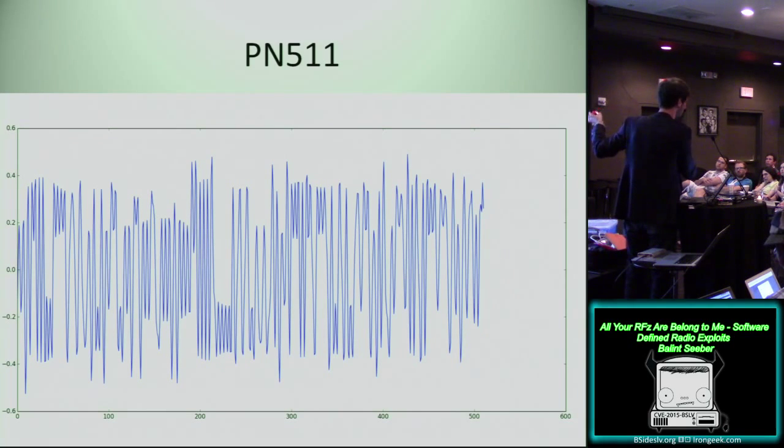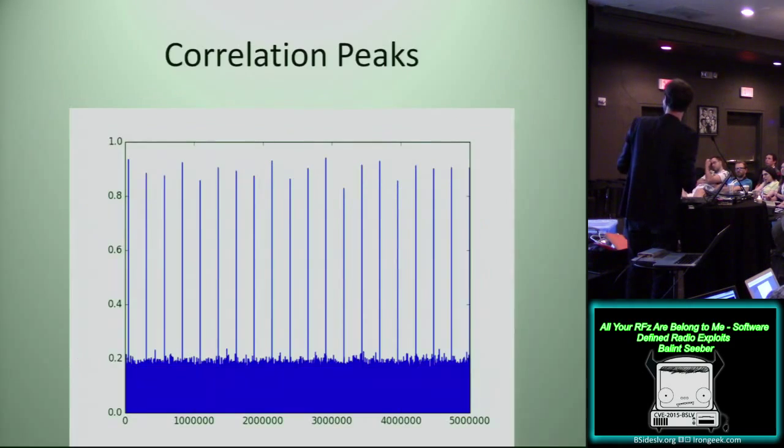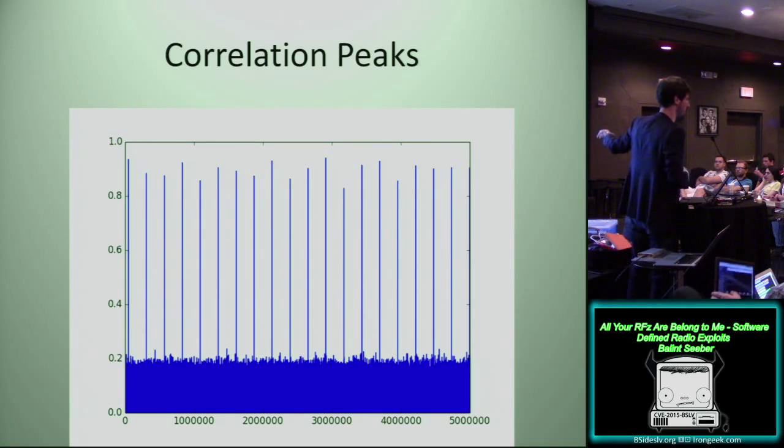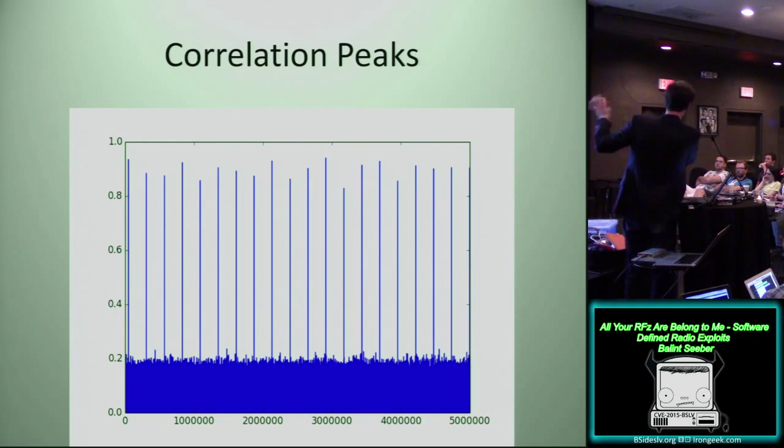This is what it would look like if you received just that little bit of signal. So if you actually have this as your reference, you can then go and receive a legitimate TV signal, and correlate this sequence against your known TV signal. And what you get then is periodically, every single time that field sync comes through your television stream, you'll get this really strong correlation peak. And this is what you expect. This is positively identifying that we are receiving a good ATSC signal, which is cool.